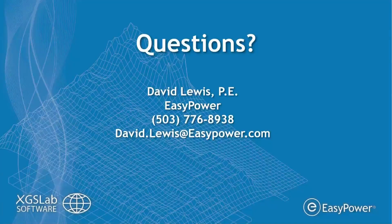Now, the equipotential plane assumption makes that 1,000 volts propagate everywhere, but in reality, if you energize one far corner of a system, there's a voltage drop through the soil and through the metallic conductor from one corner of your grounding system to another. That's what XGSLab will do: it models that voltage drop.